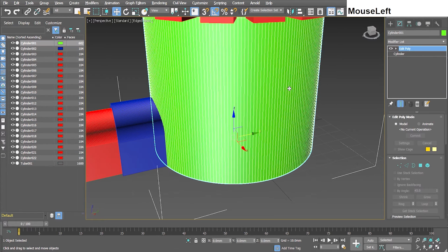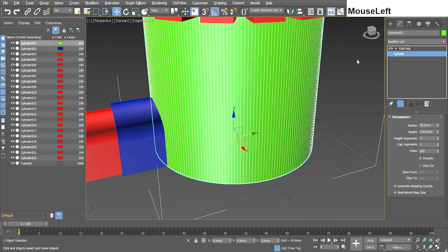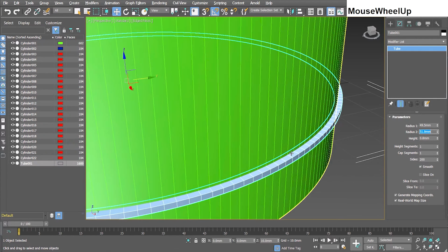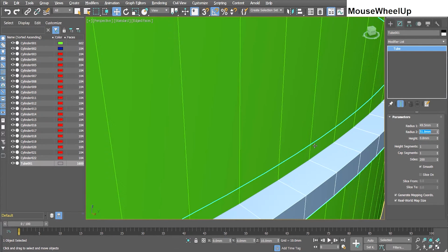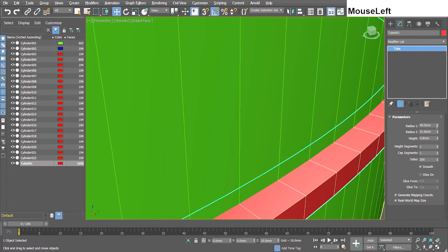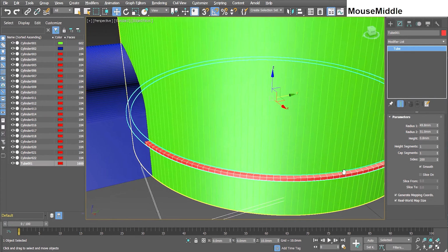I'm going to click back to here, because let's say I don't remember on that cylinder how far across it is, 50 millimeters. Now I can go back to that tube, type in 49.5 and 51. And what that will do is have it cut inside just a little bit once we subtract this out. And you know, I don't need the bricks to cut that deep, so we could do 49.8. That'll make it easier for 3D printing.